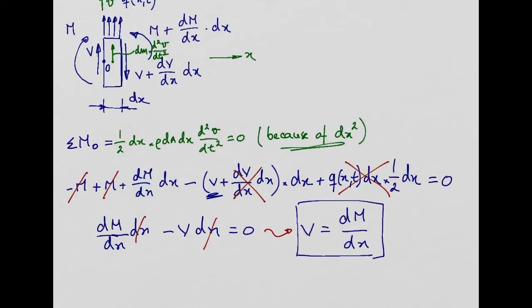which is something that I think I did in statics in year 1 for you, right? I remember I talked about this. You can get the transverse shear force from the derivatives of the bending moments. Remember when you did the bending moment diagrams and transverse shear force diagrams for the beam deflection? Once you have the bending moment equations, you can get the transverse shear force equation by doing the derivative of the bending moment. That comes from the equilibrium of the moments about point O, right?